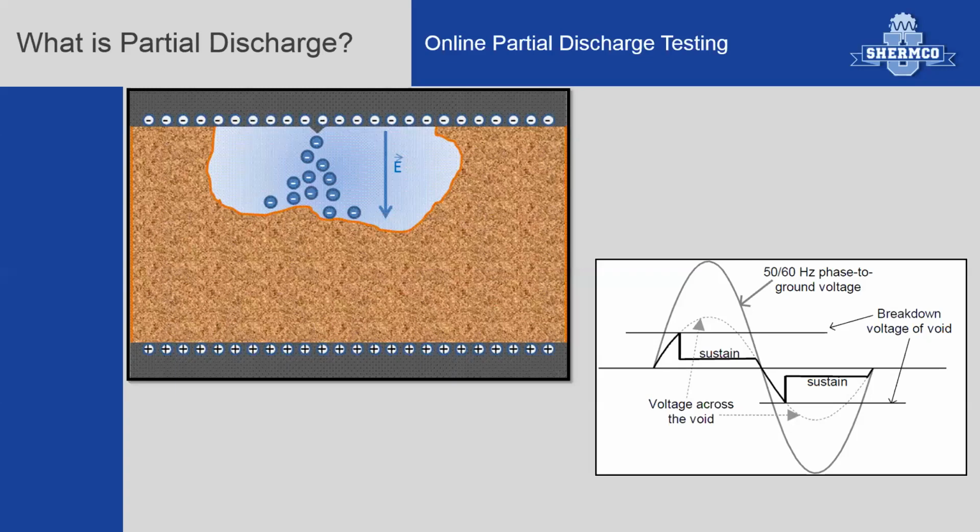When the voltage stress exceeds the breakdown strength of a certain section or portion of insulation, a partial discharge begins and continues to deteriorate that insulation. When partial discharge occurs, various physical and chemical changes may happen, which produce emissions that we can detect, localize, and characterize to provide the information needed to prevent insulation failures on medium and high voltage electrical equipment.